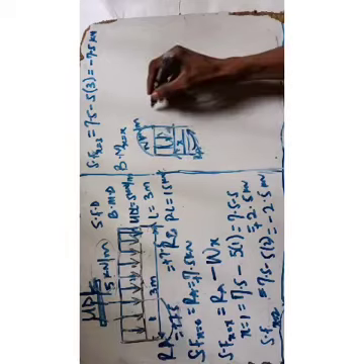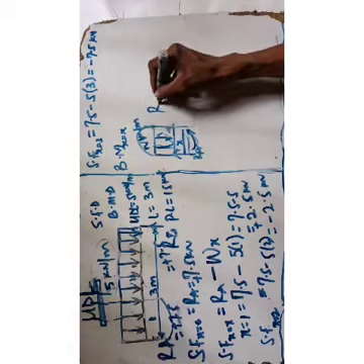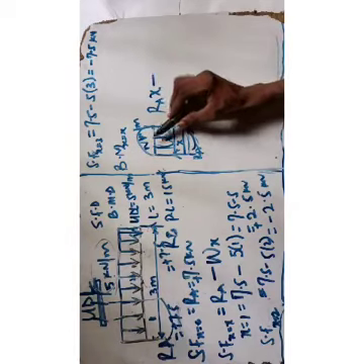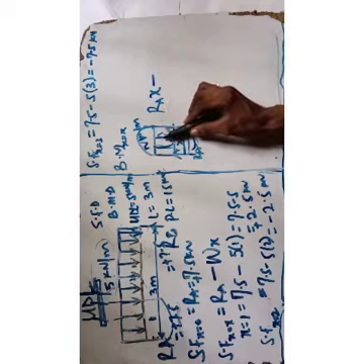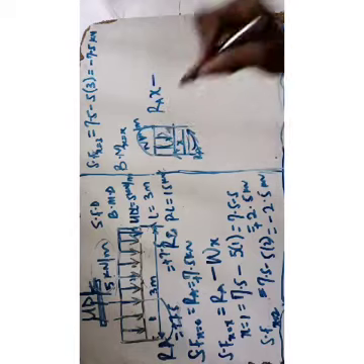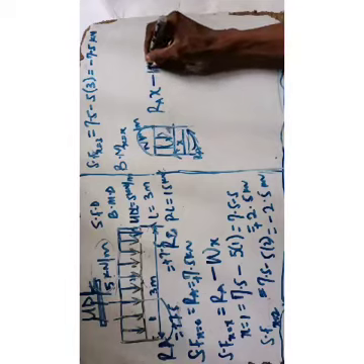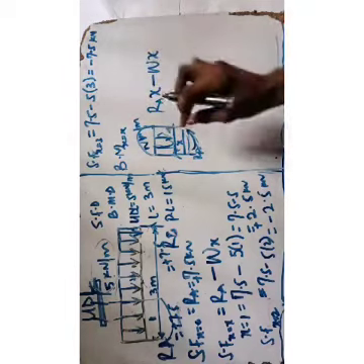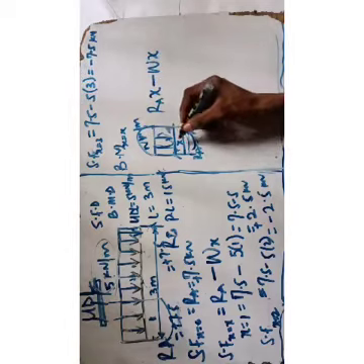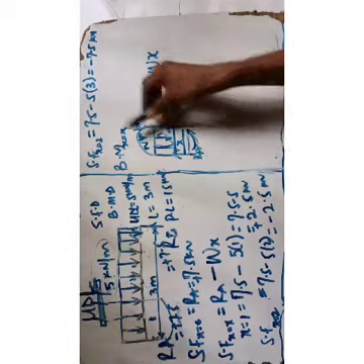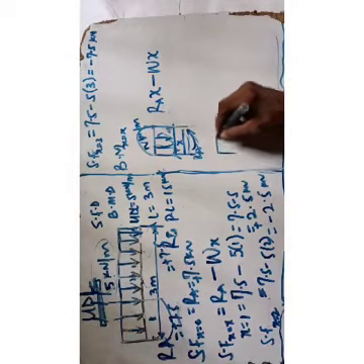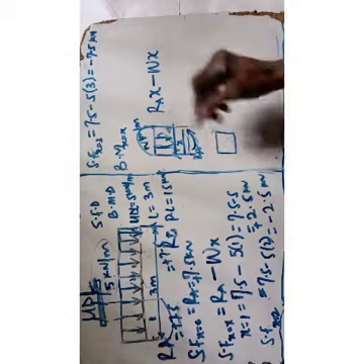So what will I do? Taking moment, that will be RA times this x minus this weight is the one acting here, okay? So I'll come back to point load first. That will be minus W times the total length. Once I convert to point load, that is length times breadth, area, the diagram will change to be this, and it will always act at the center.